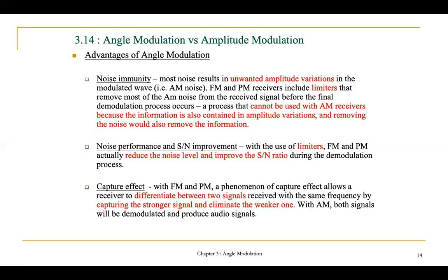For FM and phase modulation, the capture effect allows the receiver to differentiate between two signals, capture the stronger signal and eliminate the weaker one. While for amplitude modulation, both signals will be demodulated and produce an audio signal.